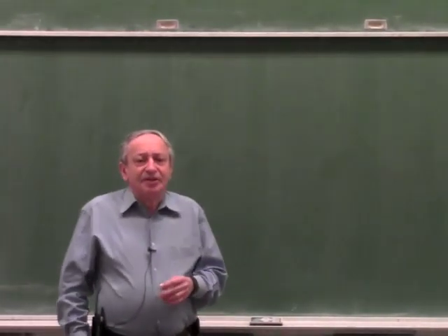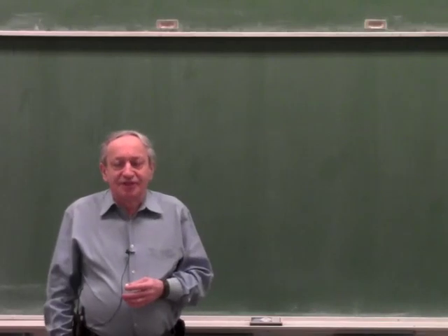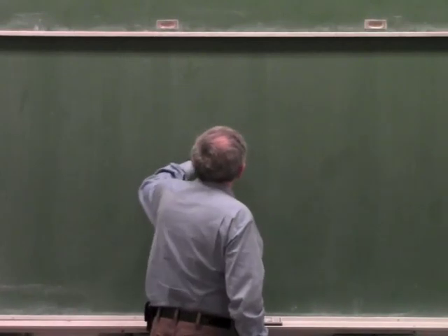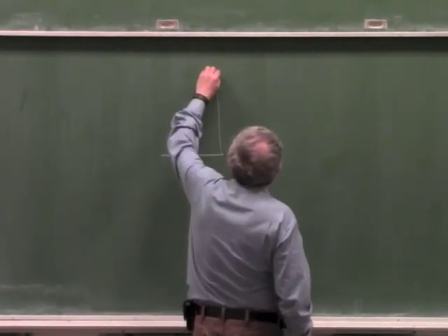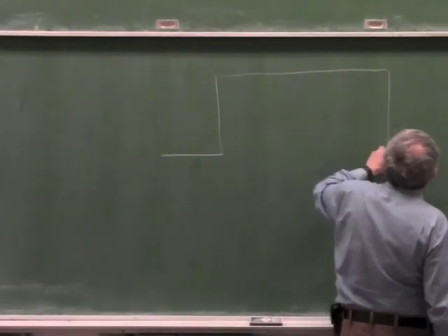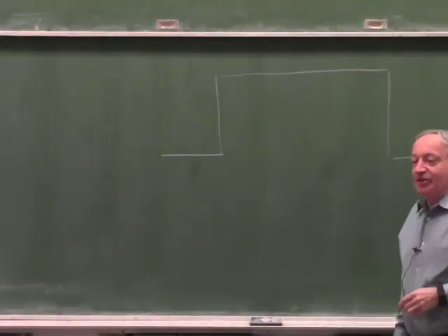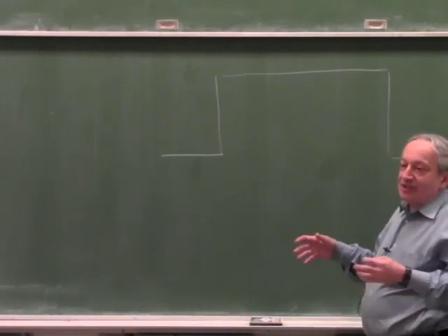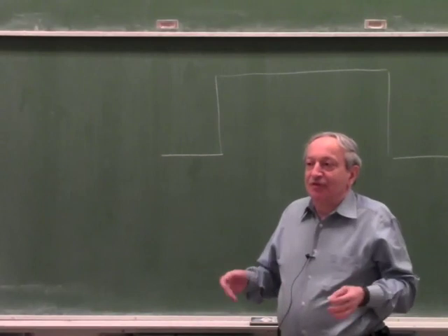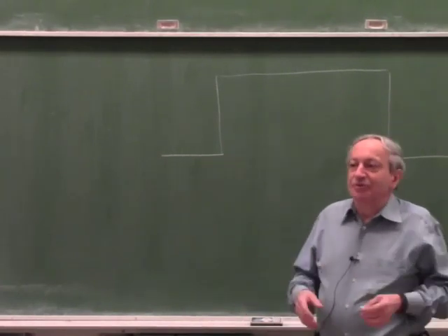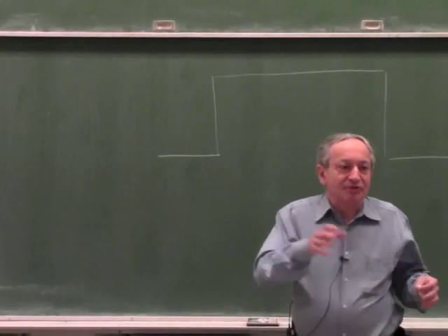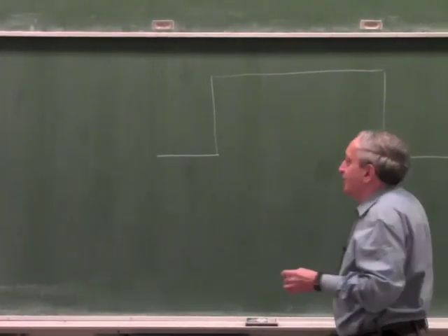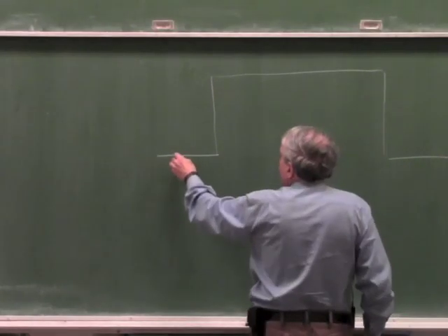So the basic requirement of a servo system typically is that it gets a command, and it doesn't matter if it's a position command or a velocity command or any kind of command, it gets a command to do something, and the actuator has to follow this command. In the simplest case, it's some kind of position servo. You have a stepper motor with a lead screw, or a DC motor which moves a robot arm, and this is a position command. And then you look at the response, and the response of the servo will look like this.